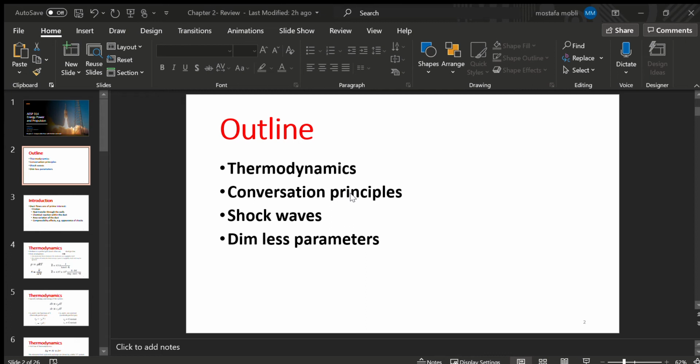So the next step is to use the concept of entropy and the Clausius inequality and come up with an equation that helps us calculate the entropy, right? Because in the form of that inequality there's no way we could calculate the entropy of the system or the entropy of the two states of the system. To do so, we have to go back to the work done on the system or by the system, the elemental changes in work.